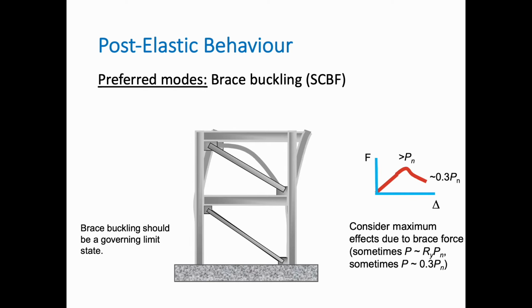And a little bit more complicated is when the brace is buckling with a reverse load. Now we have, in fact, a steel degradation. So what's happening is at the beginning, the bracing buckles and it reaches its maximum buckling capacity. But as the load goes back and forth, it reverses to the tension and then compression again.